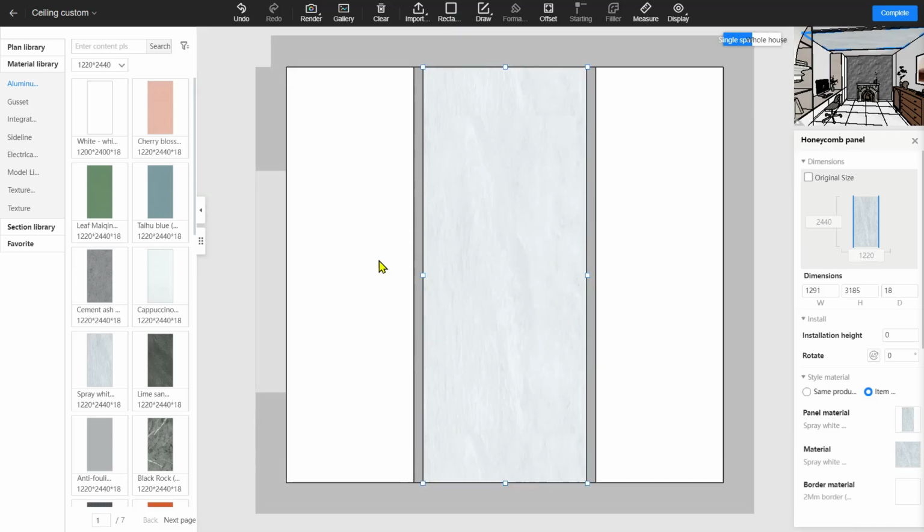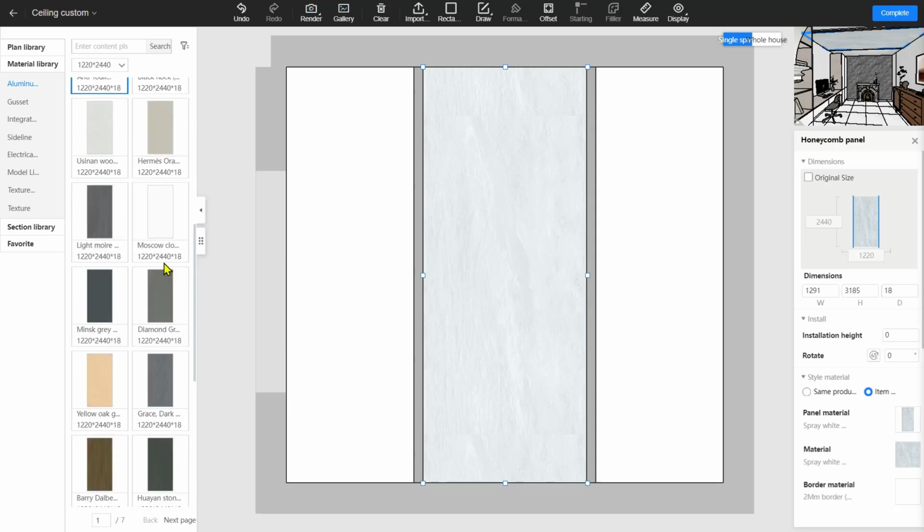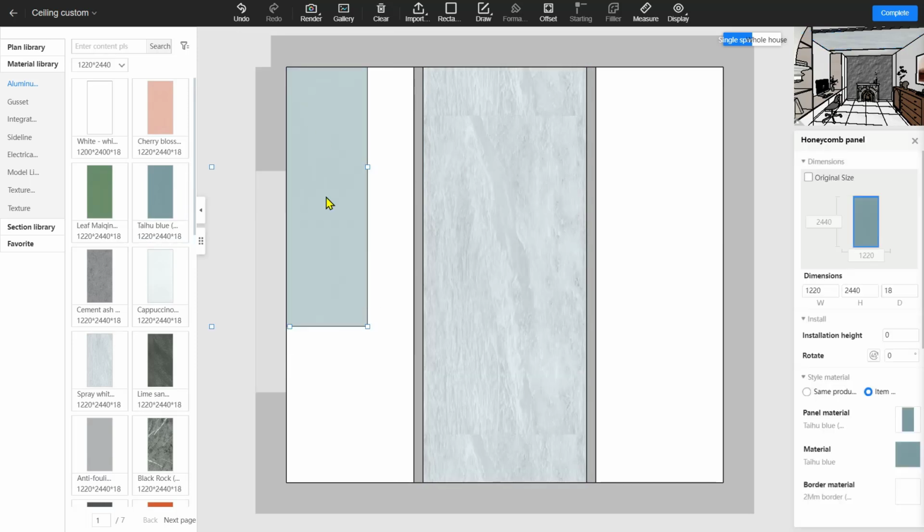We are going to place here. Then you can find the other side of the board to place inside. I'm just going to drag and drop this one in. Then first you can change the size at the right side. Its width to be 1000. Its height to be like 900. Then hit the T key to move it. 0 and to this part 0. So the first one is set well.